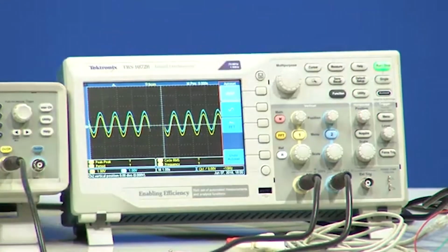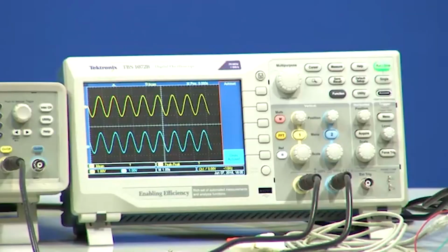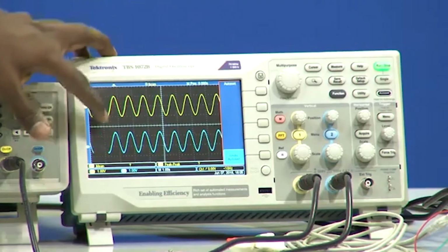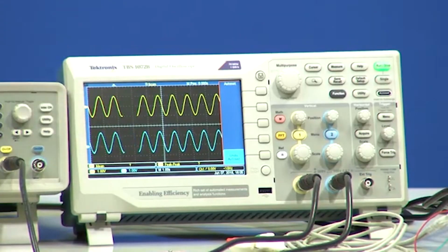Okay. So, there is a slight shift of our output, so that we can adjust by changing the pot, right. So, let me change the pot value. When we look into the CRO, we can see we are getting both input and output signal. Now, what we have to do is see whether this particular circuit is filtering out the 50 Hz component and other frequencies are passing or not.